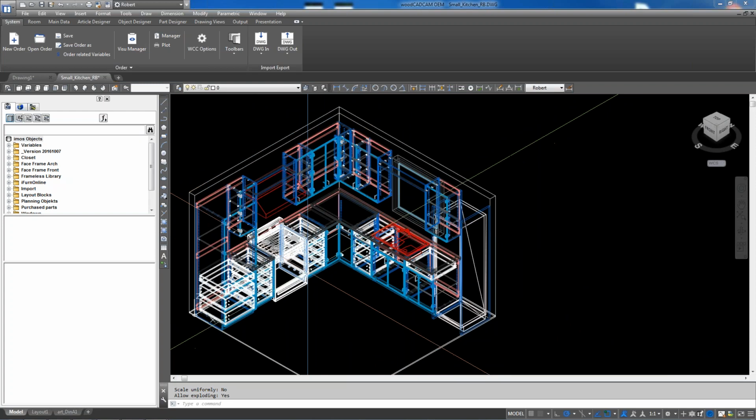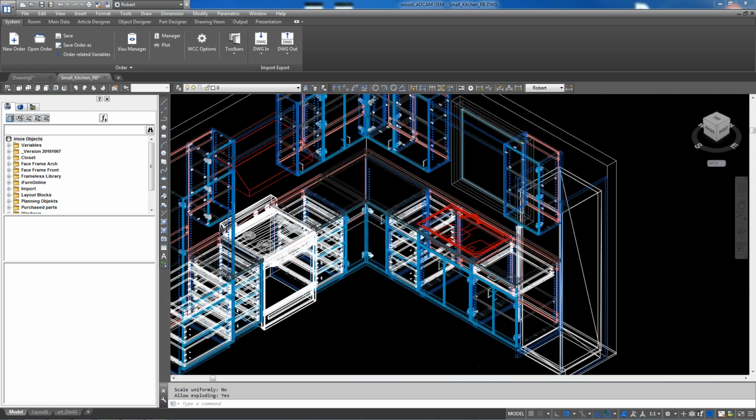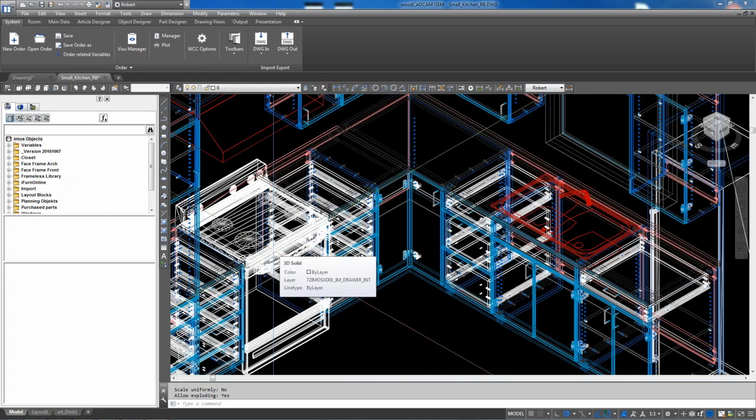Do a list on the range. Yeah, but this range is from the library, from WoodCAD/CAM. Okay. So it's not the one, because I couldn't bring in another block. My guess is they have the same block reference. So once you bring a block reference into a drawing, that block reference is set. If you bring in another drawing that has the same block reference, it's going to just pull up the original. Without opening both drawings, I can't really tell. Okay. All right. That's good enough.